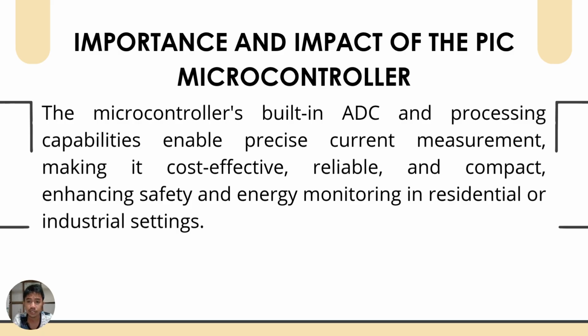So this is the spotlight of the microcontroller. The PIC 16F877A is ideal because it has a built-in 10-bit ADC, which offers good resolution for analog signal conversion. It is also relatively low cost and consumes very little power. It is programmable, which means it performs real-time data processing and also controls the display. These features make the system compact, affordable, and reliable.